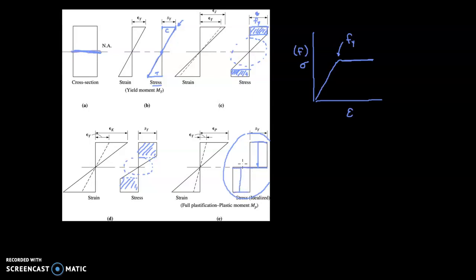This is the point at which the steel beam is considered to have completely failed. This is the plastic moment, MP. And MP is equal to the yield stress multiplied by not the regular section modulus, S sub x. We called it just the section modulus before, but technically it is the elastic section modulus.